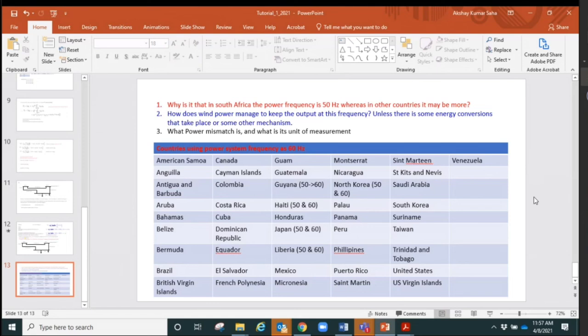Again, it will come to the scenario of power factor. When you keep your P constant and increase or decrease your Q value, it will also change the power factor. It will become more lagging. If you keep your P constant and increase the Q value, the power factor will start decreasing, and how far you go, that you will decide. Now if you are at 0.9 power factor lagging, you can go to 0.88, 0.87, 0.85, it's okay.